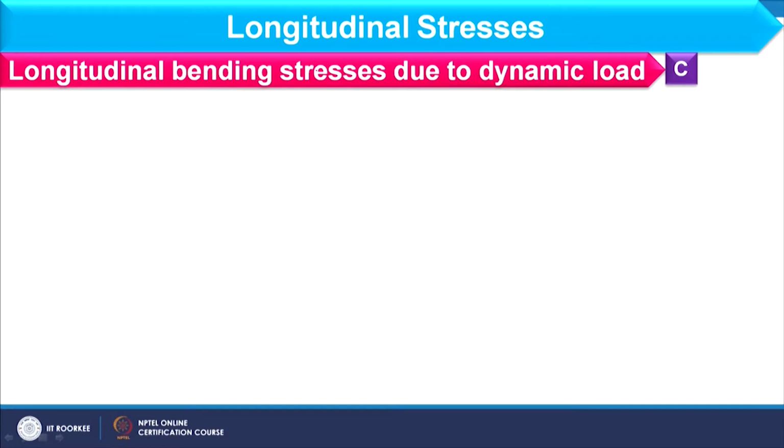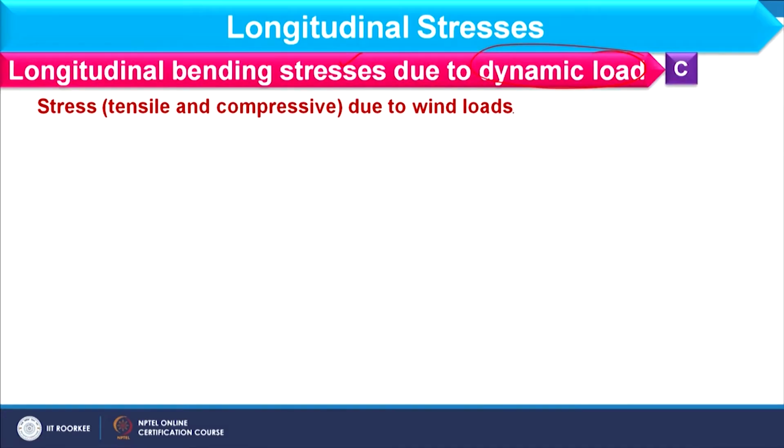So, here I am considering longitudinal bending stress due to dynamic load. So, what is dynamic load? Dynamic load means which is continuously changing along the length. If that load is changing, we consider that as a dynamic load, such as wind load as well as seismic load. So, let us first focus on the wind load. Stress due to wind load should be tensile and compressive both. Because